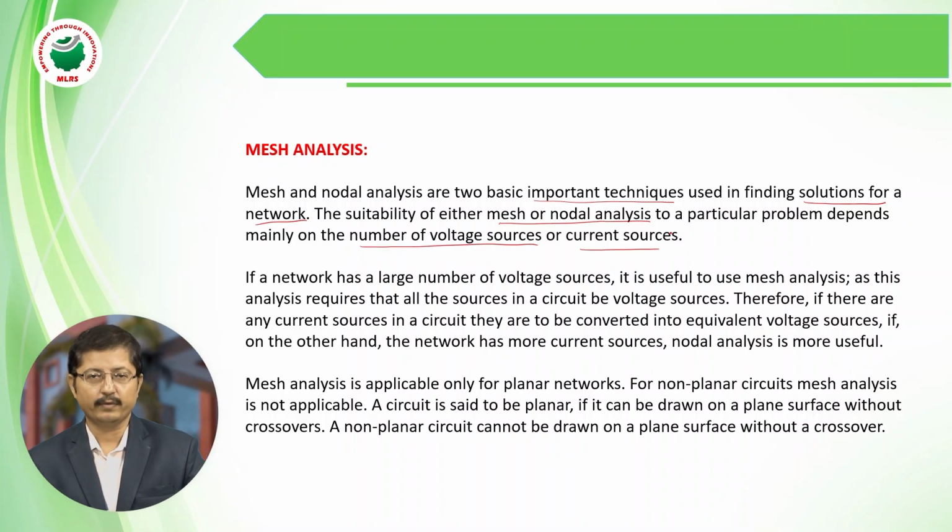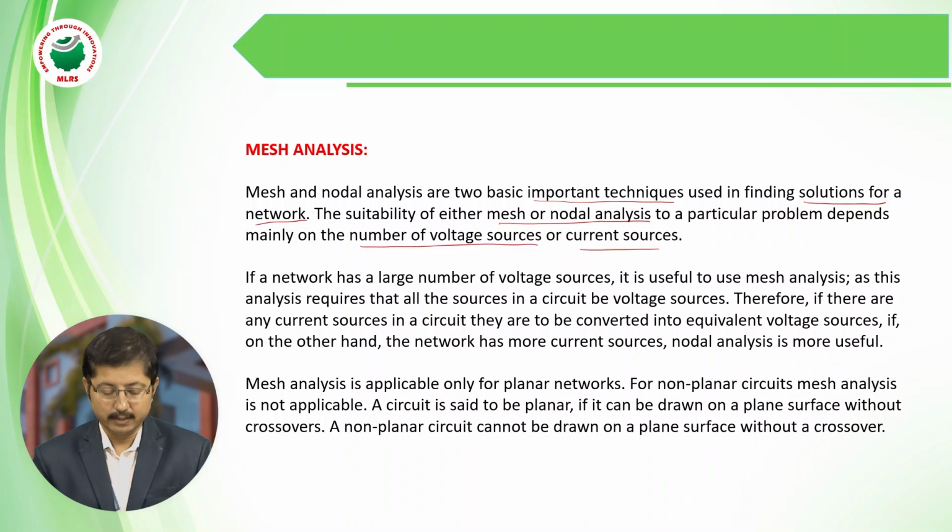That means we have to decide which method we are going to apply. For that, we take into account how many voltage sources and how many current sources are there in a circuit. Based on that we can choose mesh analysis or nodal analysis. So that is the point here. If a network has a large number of voltage sources, then we use mesh analysis.